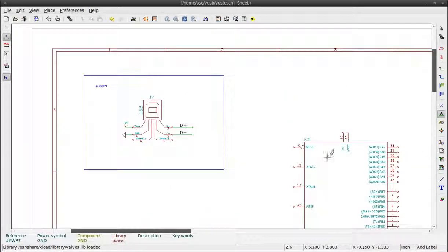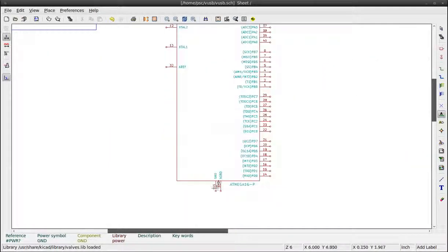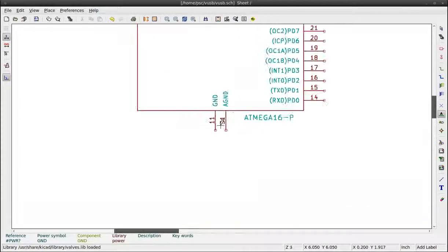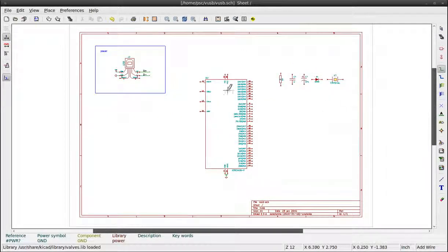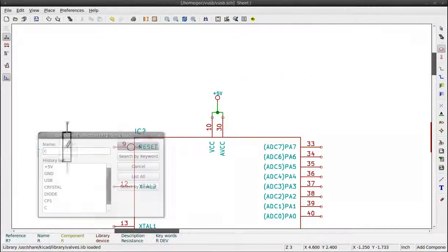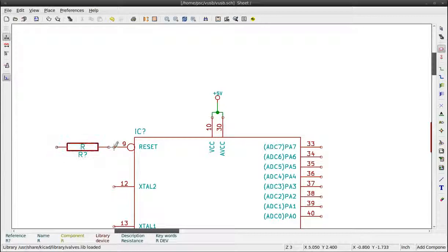Click the middle mouse button to recenter the schematic at your cursor position. Use the mouse wheel to zoom. Connect the ground like so. When 2 or more connections touch, a junction is created. Same principle for the 5 volts. Now a resistor connects to 5 volts. Rotation with R. W to connect.